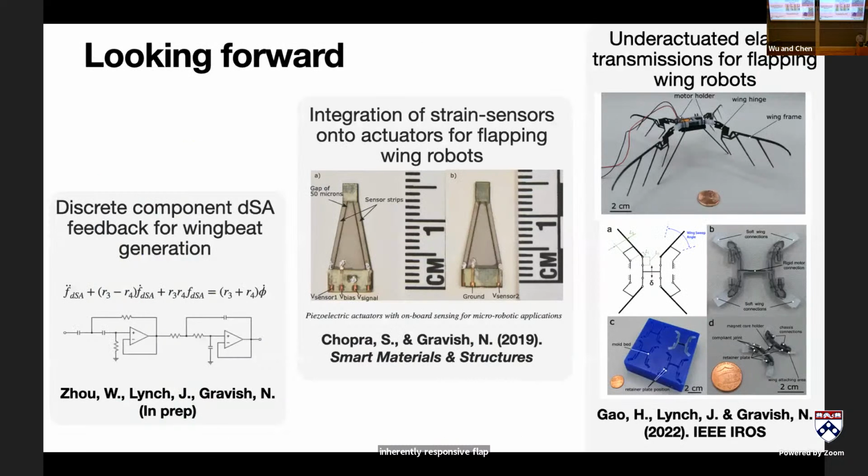We've been working on embedding actuation and sensing into the actuators themselves, right? This is all a proprioceptive type feedback where basically the muscle is just watching its own stretch and then applying forces. All of this can be emulated in very simple analog circuitry, ideally embedded in the mechanics itself. And I think that's really where this would be interesting. If we're just emulating this response, then why not use other forms of actuation? And so we've got a lot of different platforms that we've been playing around with how to embed these feedback properties into.